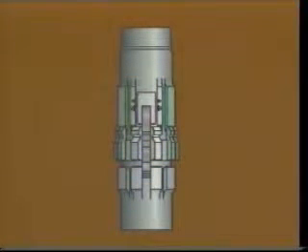Expanding type hangers are generally used for smaller casing strings where the bit size closely approaches the casing ID. Expanding type hangers utilize spring-loaded steel sections that lock into the mating downhole hanger. Both types of hangers provide fluid passage for circulating and cementing.